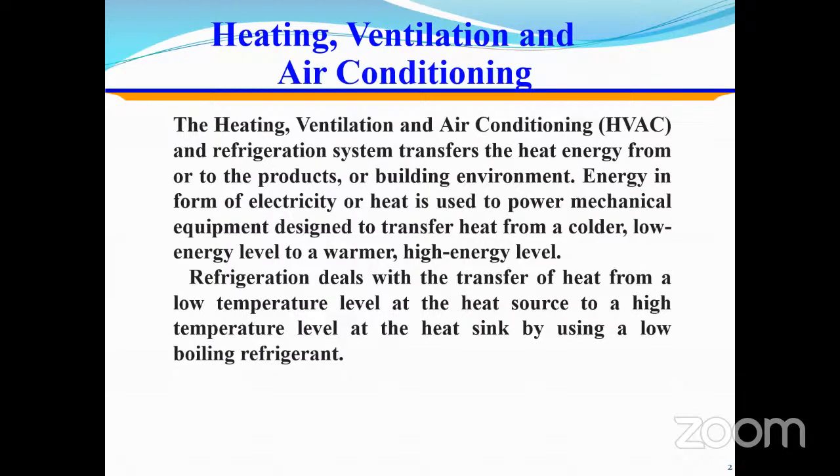See, the term is commonly used for heating and cooling. The refrigeration deals with the transfer of heat from a low temperature level at the heat source to a high temperature level at the heat sink by using a low boiling refrigerant.